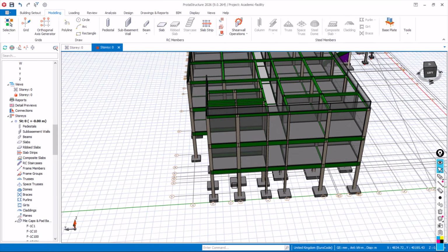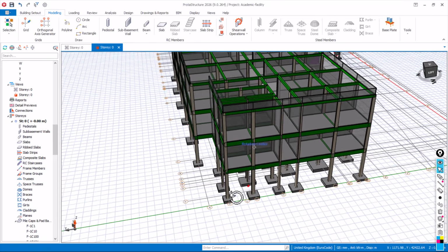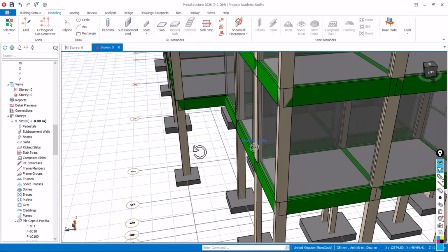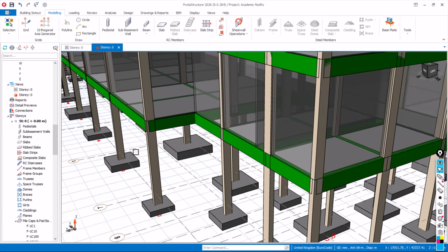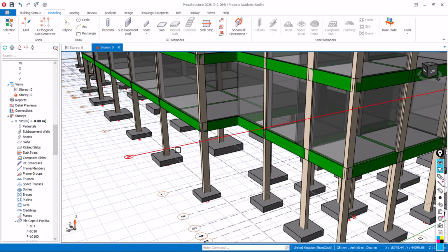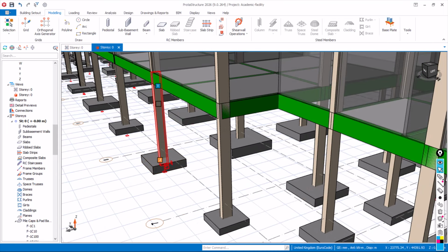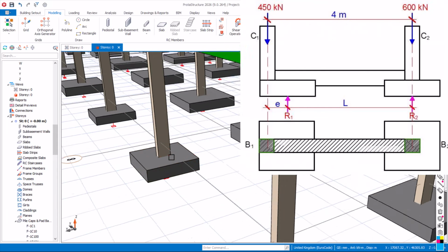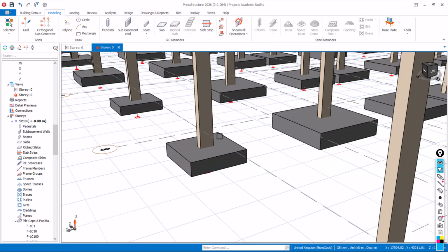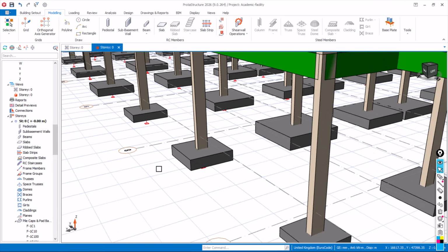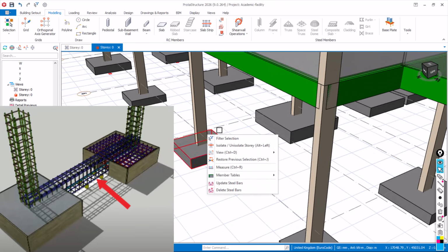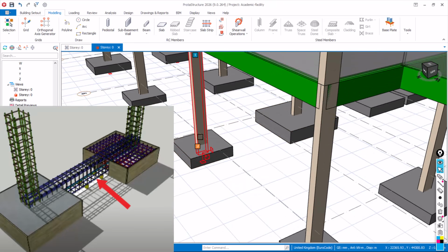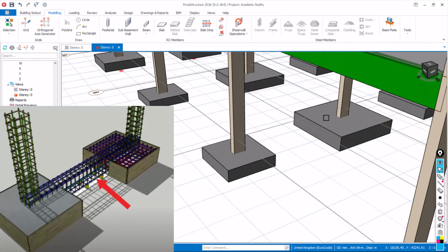But the client says no, so that is now what gave room to another engineering justification based on foundation design. So we then say, okay, we can still design an eccentric footing having a strap beam. So based on that, we are going to design an eccentric footing that gives room to a strap beam to be able to balance the counterweight or to transfer the load from this footing down to the interior footing.